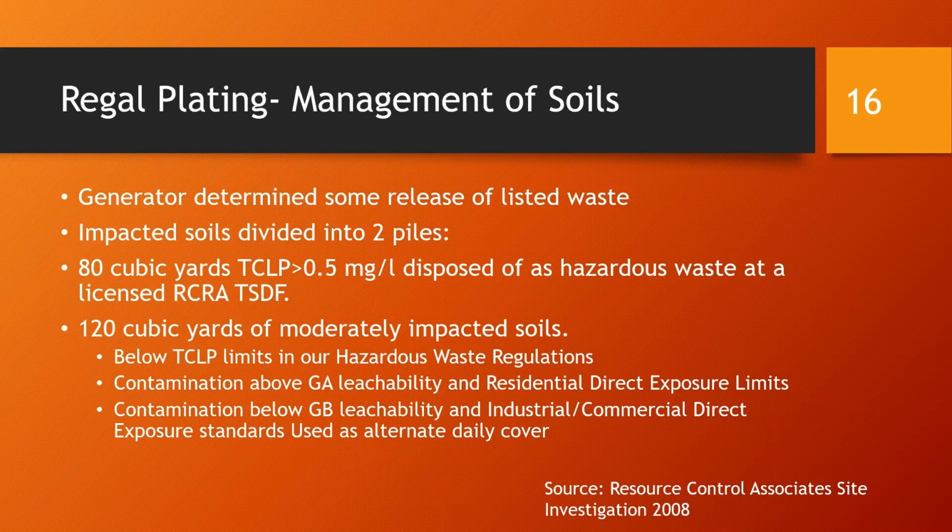The impacted soils were divided into two categories, and one was a soil that flunked TCLP for, trying to remember, I think it failed for cyanide, and that had to be disposed of as a hazardous waste. But they had a larger volume of moderately impacted soils that were below TCLP. They were above a leachability standard and a residential standard, but they were below the leachability standard for GB aquifers, which this is a GB aquifer, and they were below industrial commercial standards.